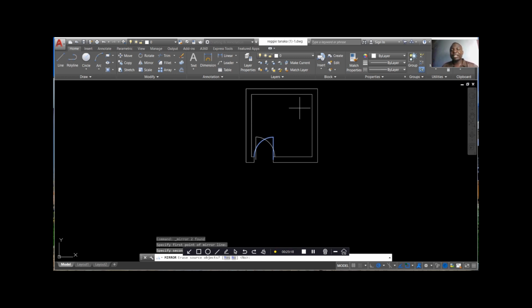So there's no privacy in this room. As a bylaw, you open into privacy. So this is wrong, the white door that I've put that opens to this wall is wrong to put like this. Actually, your plan will not be approved. The plan will only be approved when the door is opening into privacy.